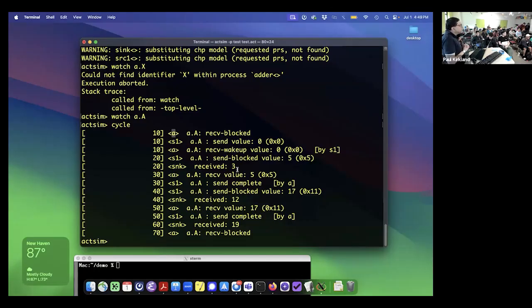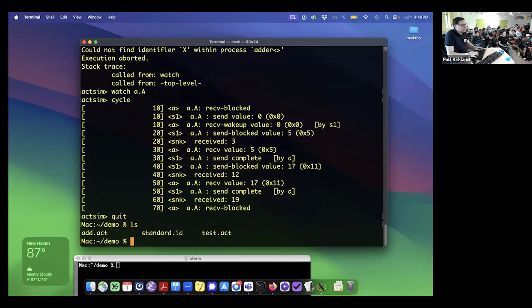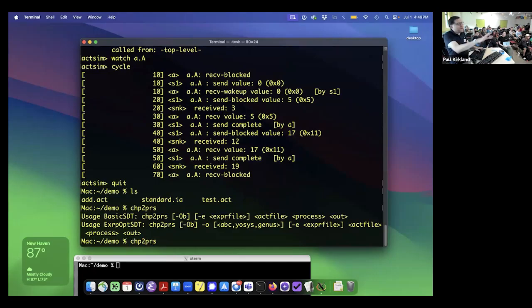And what do you do next then? What I do next is I'm going to turn this into a circuit, CHP to PRS. This is actually a bad version. We have a new version that's much better, but it doesn't really matter. So let's do a bundle data circuit. This is how you define your protocol. You tell the synthesis tool what protocol you want. So your -B is bundle data. That uses the request, ACK and data bus, right? You can say which logic synthesis tool you want for all the expression optimizations. I'll use ABC.